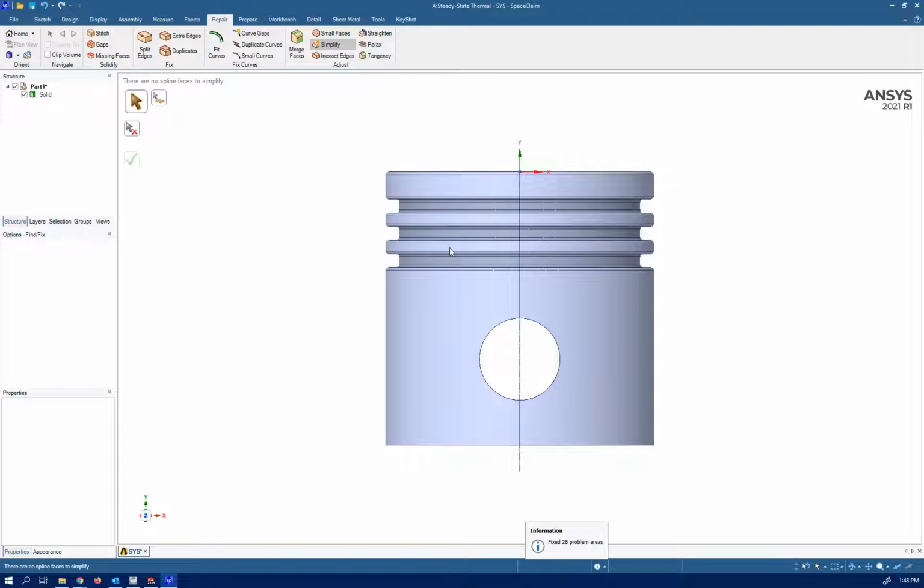Nothing changed. Just connected the geometries. If it's a line, we divided it into 5, 6 different parts. They're connected now. If there are some surfaces, now they're connected. Let's see any small faces, because sometimes when you're drawing, there's like a 0.5 millimeter small surface somewhere, which just appears there, or when you're drawing you make a mistake. So no small surface. How about inexact edge?